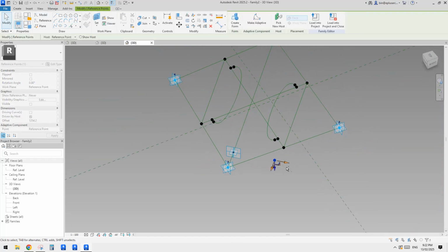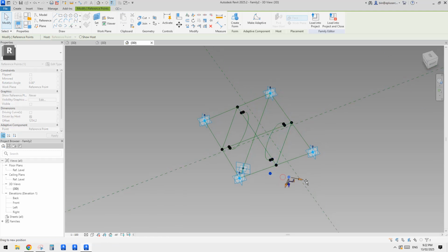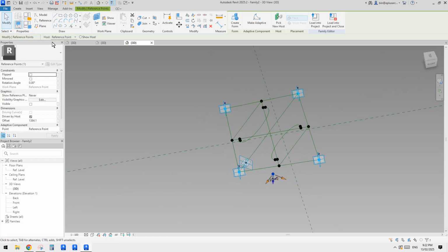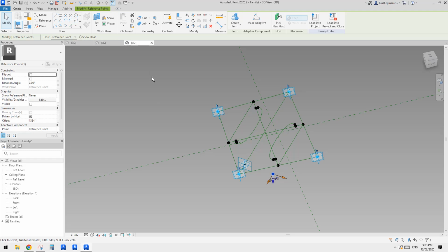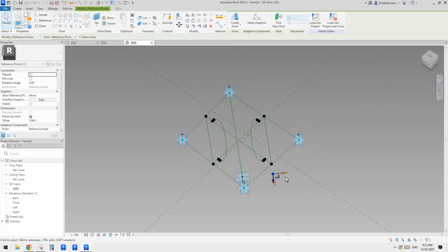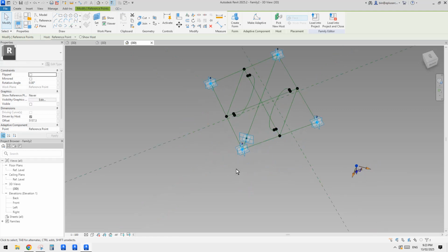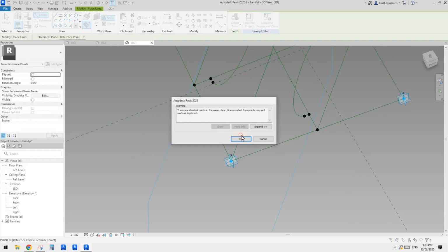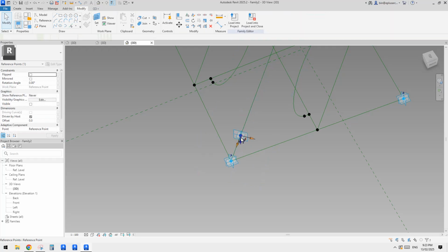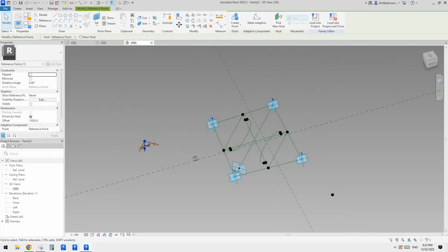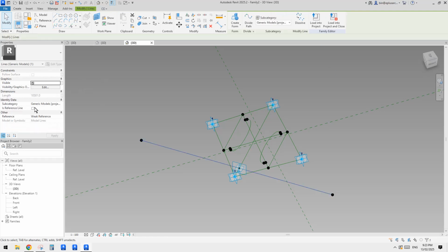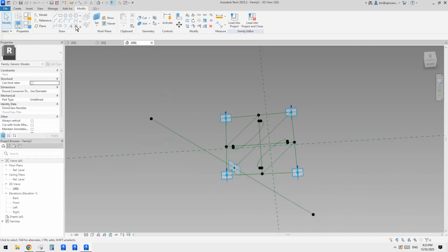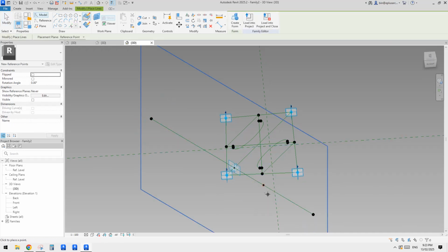Here I didn't use a reporting parameter to control where it needs to be, because there's no way we can do it. You can see when you select this point there's no option for intersecting or whatever. So I just extend this one, move it a little bit further, and then place another point you draw on work plane again, pick the vertical work plane on this point, place a point and click OK, and this time move it the other way. Okay, the other direction. Now we can select these 2 points, create a spline by points, make a reference line, and then use a point you draw on face, place onto this.